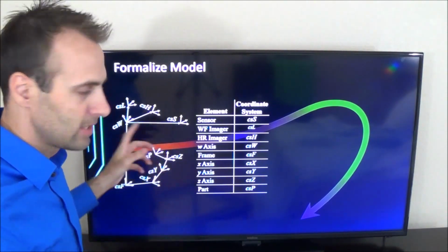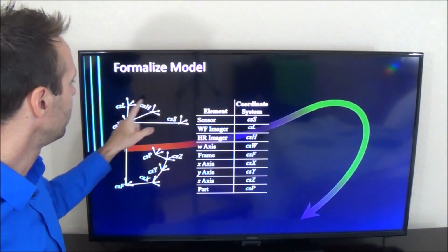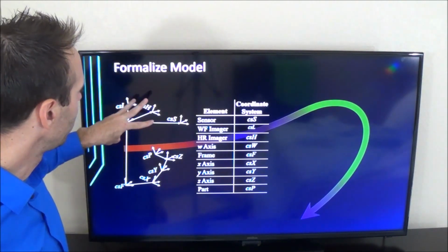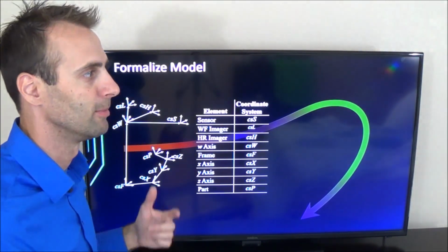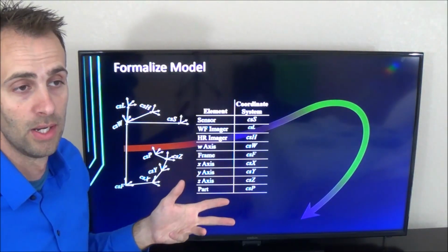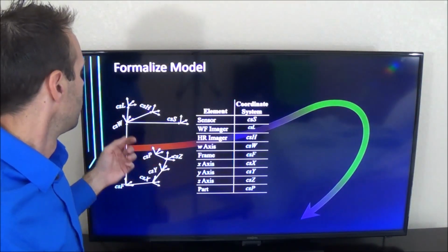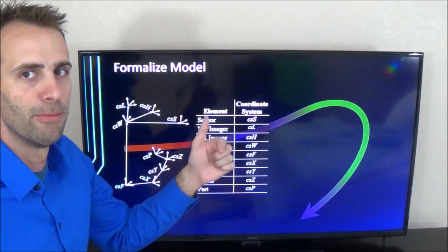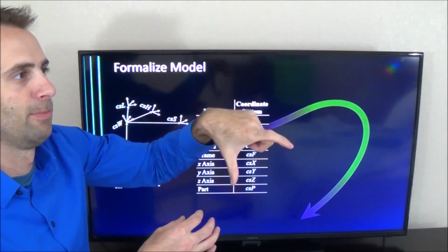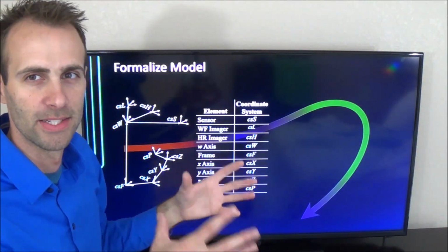So, for example, in this diagram here, I lay out all of my machine elements, but then you'll notice on this W axis, I've got 3 different elements here. So these would correspond to actually 3 different tools. And in this case, they're all different sensors on a measuring machine. So the equivalent to that would be if you had a touch probe on a 3D printer that would come down and feel the table out, and then it would switch back to the printing head and start printing where you want, or maybe you want to know where your vise is or whatever.